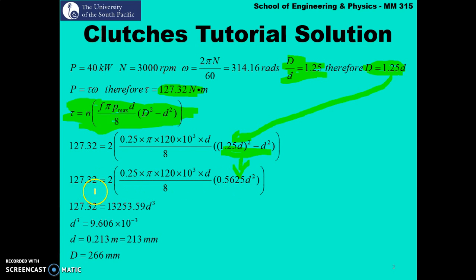So if we further simplify, your torque 127.32 is equal to, evaluating all of these, 0.25 times pi times 120 kilopascal divided by 8 times 0.5625 times 2. You should be able to simplify the above expression to this. So 127.32 is equal to 13,253.59 d cubed.